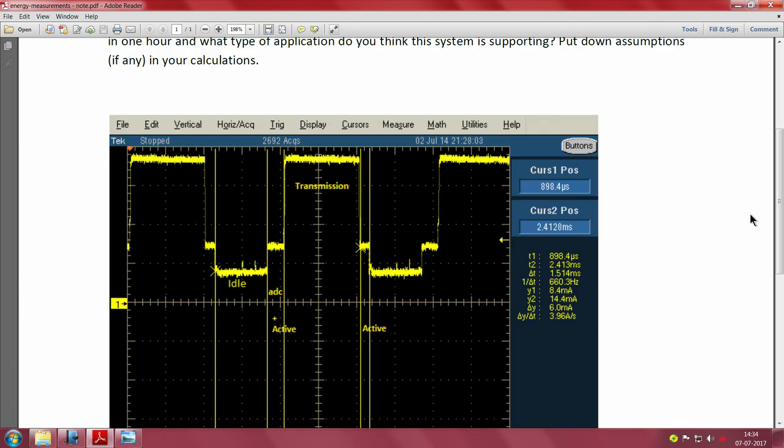The first part is indeed the transmission that you see, then it is going to one other mode, perhaps a lower current mode, which could be reception mode. You do a transmission at the highest possible transmission power, it could even be plus 20 dBm, and then you get a higher peak. Transmission is done for a certain duration, and all the numbers are on the right side, so you can look up those numbers. It is done for a significant amount of time.